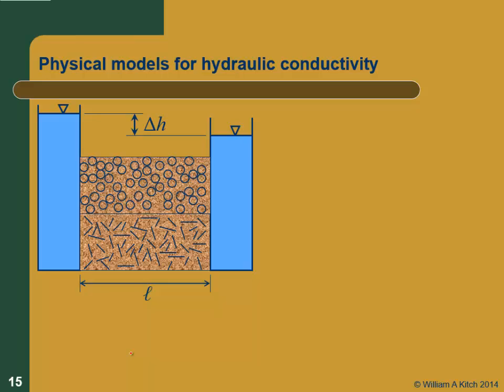Well, those are nice, but those are all just empirical fits, and there's some newer ones out there. There's one by Massman that's just a power series fit that includes the percent clay, the percent sand, and the void ratio. So there's some other newer ones out there, but they're all just empirical fits. None of them really deals with the fundamental soil properties that are affecting hydraulic conductivity.